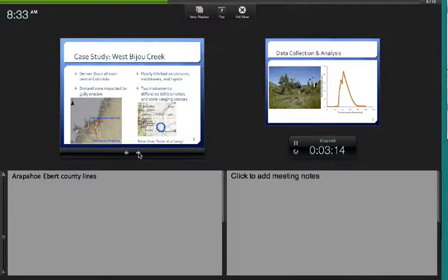And I'm going to focus in on this picture. We have a difference infiltrometer site that's right here, which was a short-term study where we set up two infiltrometers, one on a bare plot of land and one on a vegetated plot of land to measure the difference in infiltration rate. And then we have a sonic sensor stage site set up right here, which is a longer-term 6-year study on water depth, height, and stage height.